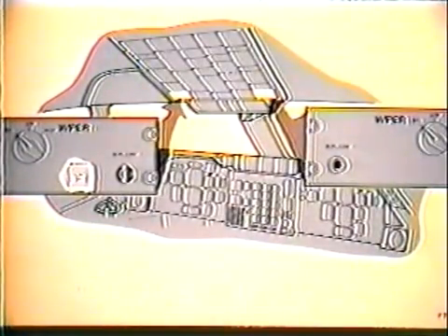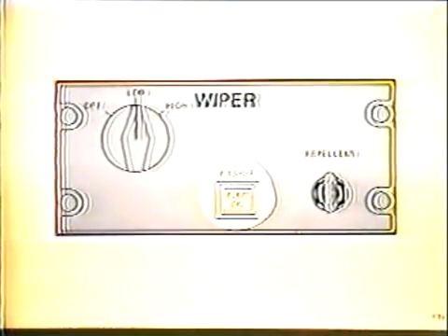Windshield washer and wipers. Both the captain and first officer have windshield wiper control panels located in the pilot's overhead panel. However, only the captain's panel contains a washer switch light. The washer switch, when pressed, pressurizes the windshield washer system and illuminates the pump on light. Pressing the switch again turns off the pump and extinguishes the pump on light.